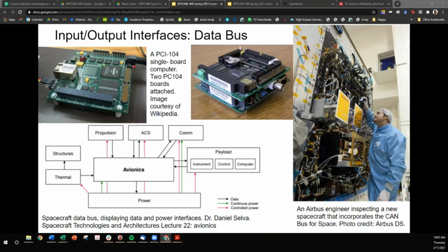There is some kind of regulation embedded in the board beneath, but the reason why we have this large stack is because if you have two, you can directly put a header from one board onto a header of the second board. In the stack formation, all of the information is going to be routed to this data bus on top, these header pins, and it can be directly transferable in this really short distance connection to the second board on the bottom.